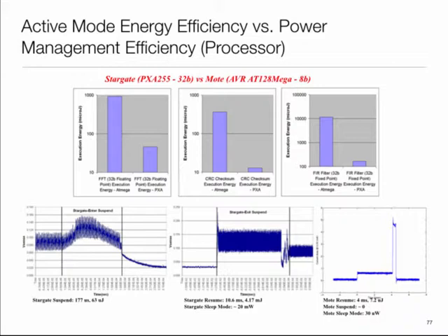So what's happening out here is these are some interesting numbers. To resume this thing, it takes around 11 milliseconds to boot up, and during which it consumes around 4 millijoules. And while it is asleep, it consumes around 20 milliwatt. By comparison with our laptops, these are pretty impressive numbers. Just 10 milliseconds to wake up, 20 milliwatt while asleep.